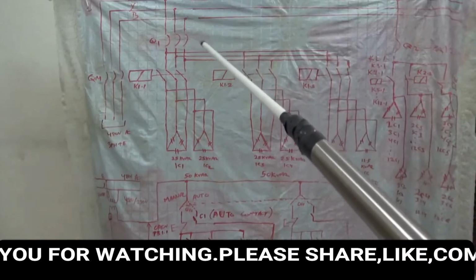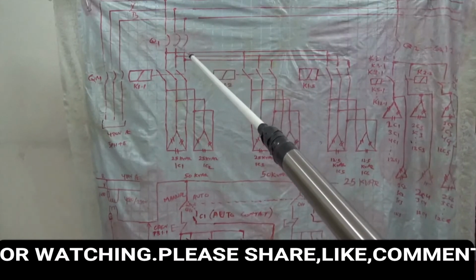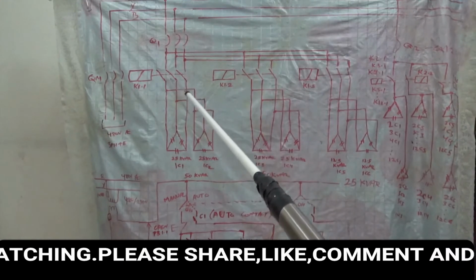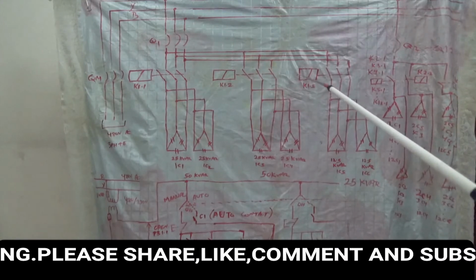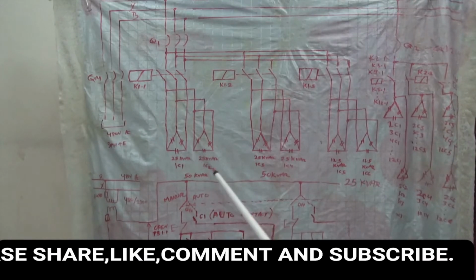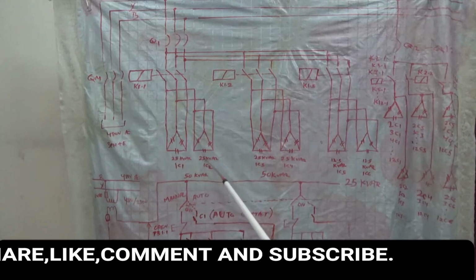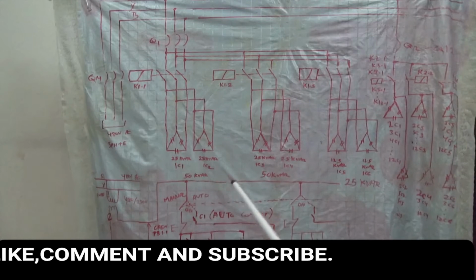Then from the bus bar there will be one branch breaker Q1. Q1 will feed three sets of contactors: K1.1, K1.2, K1.3. Each contactor will feed two capacitor banks parallel to each other. Here it is 25 kVAr, 25 kVAr, total 50 kVAr. Designation is 1C1 and 1C2.